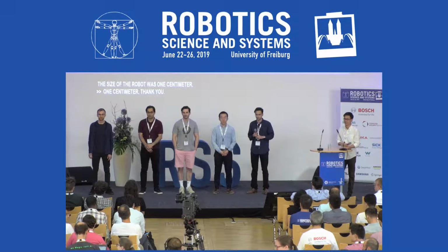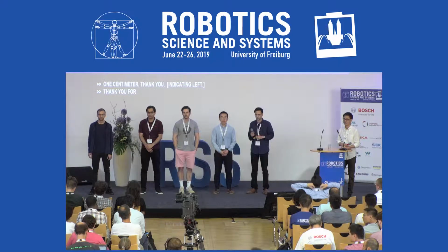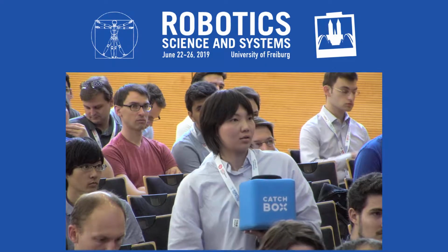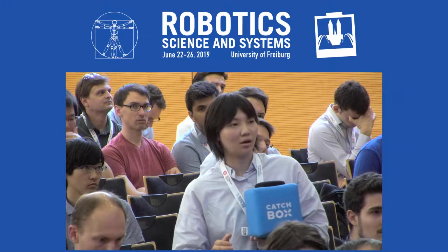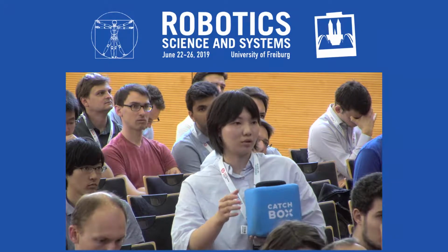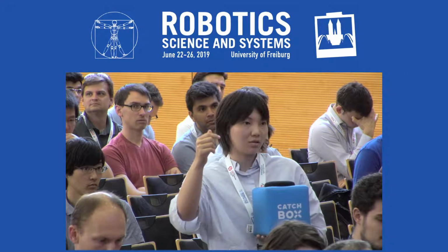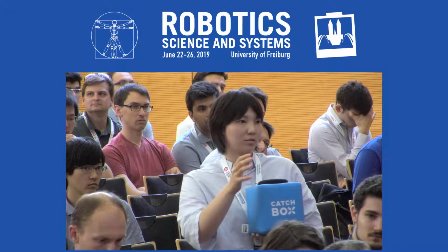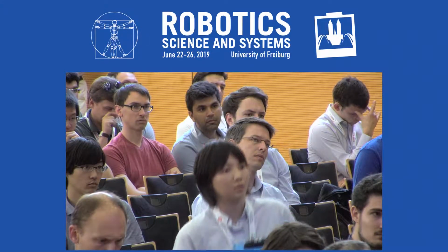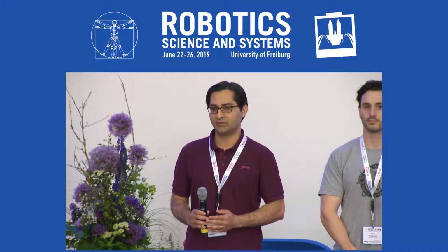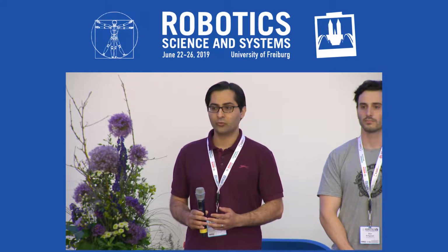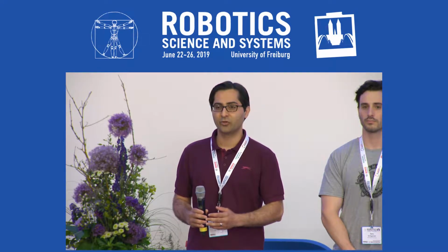Thank you for this interesting presentation. I'd like to ask the fourth presenter. How do you treat the situation of contacting a human? So the case of adding disturbance to the flexible part or changing the model. In terms of contact, you can have hard contact or soft contact. For soft contact, you basically have a spring and damper added to your equation of motion. And you can assume that it only compresses. So when it starts extending, you just put it at 0.